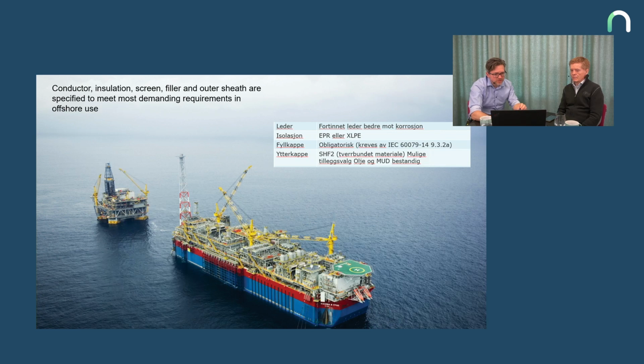Yes, I think we have mentioned this is just about the construction. There are some specifications. We see, it's in Norwegian, but the conductor requirement is that the conductor should be tinned copper. It's not plain copper. So again, here we see that NEK 606 puts the top shelf specification. We want tinned copper to make it more corrosion resistant. And when it comes to insulation, we specify the EPR or XLPE.